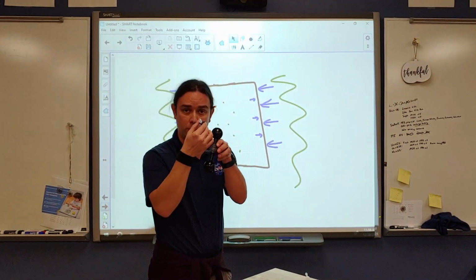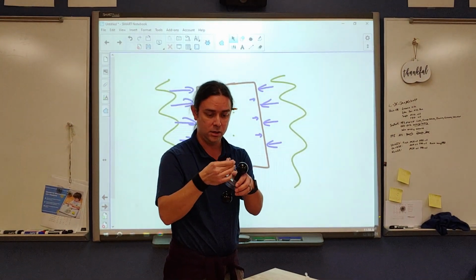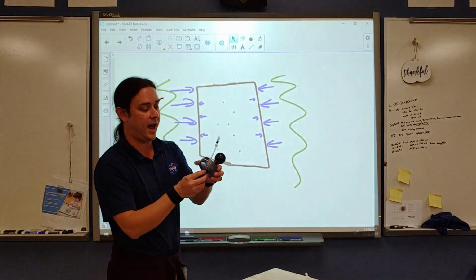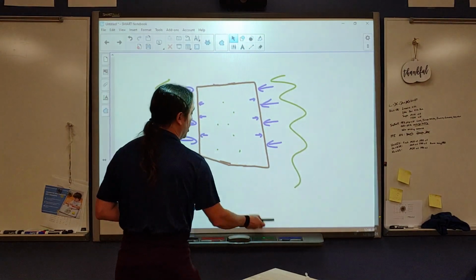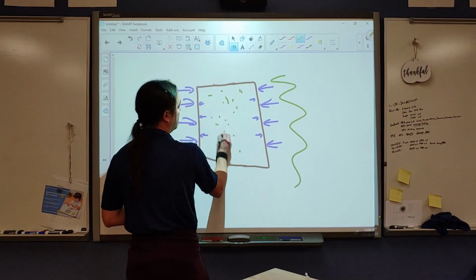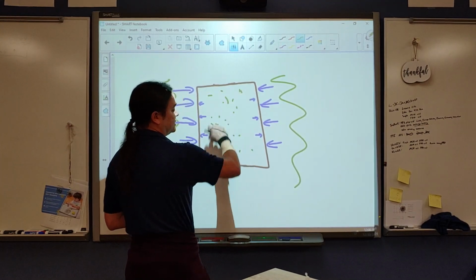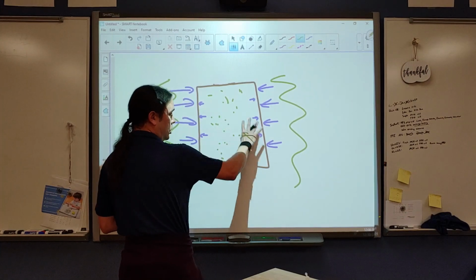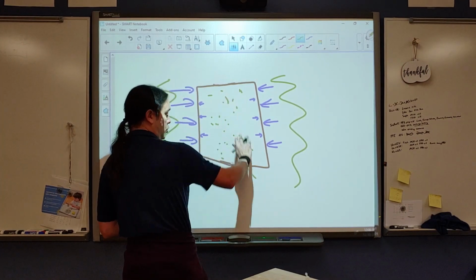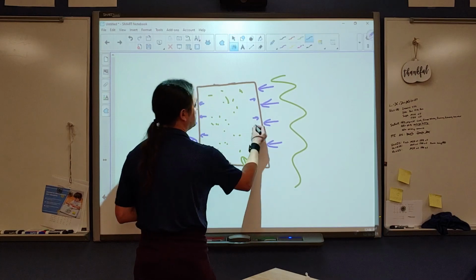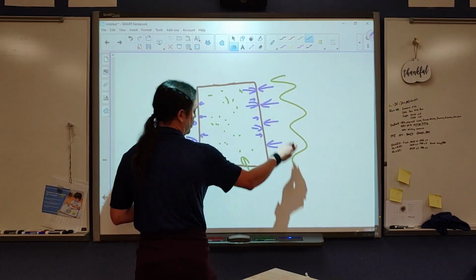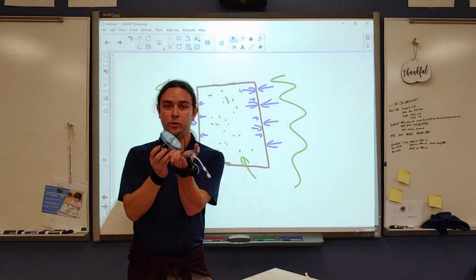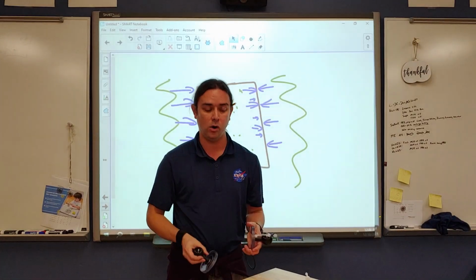Now what I'm going to do is I'm going to break the seal. I'm going to turn this. We heard a little hiss, and I felt these actually come a bit farther apart as I reintroduced a whole bunch of air. Why did that happen? Because this is low pressure, so if I open up a little line, then air will run in because there's low pressure here and high pressure out here, so it will be pushed in there, and then that brings us back up where these become better balanced. And when I do that, I can pull these straight apart. They won't hold together at all.